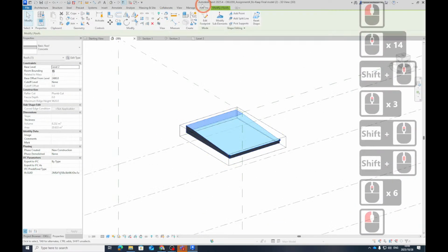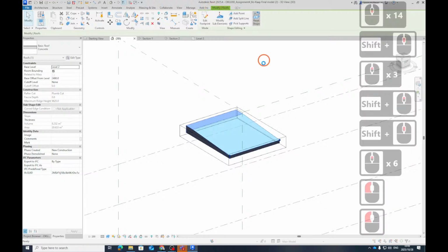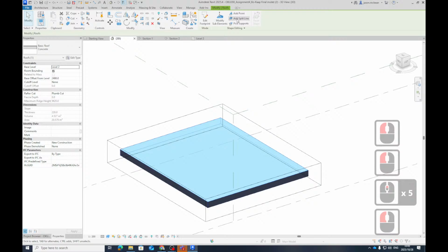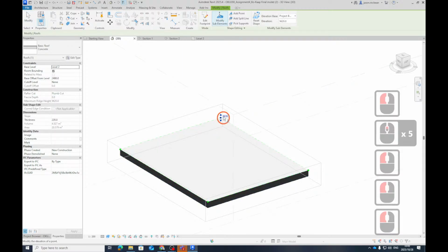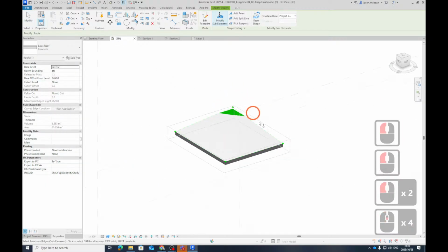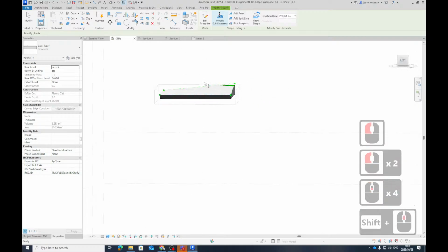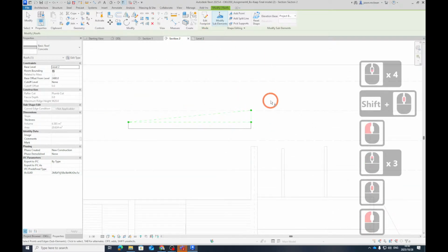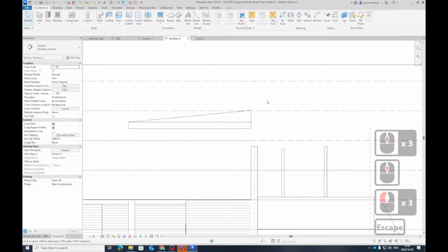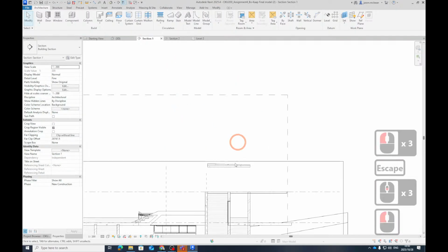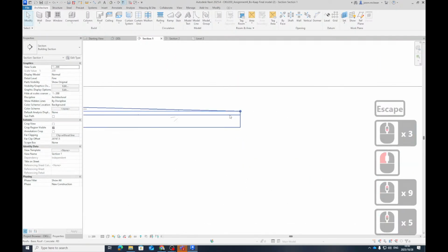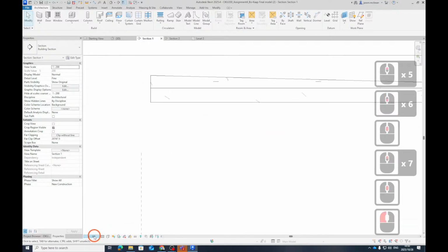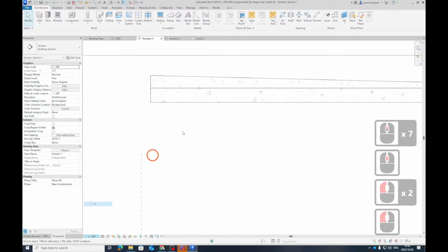this reset shape. So reset resets the shape. So say now I take just this corner and I increase just this corner. It slopes that roof. Now if I go to section, you'll start seeing the way it, and it will also, okay, that's the wrong section, this section, you'll see in cut, but it maintains your minimum 50 mil. So the screed falls in that direction. Change this to 1 to 50 or 1 to 20, whatever.